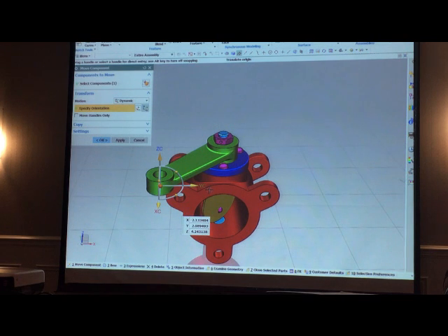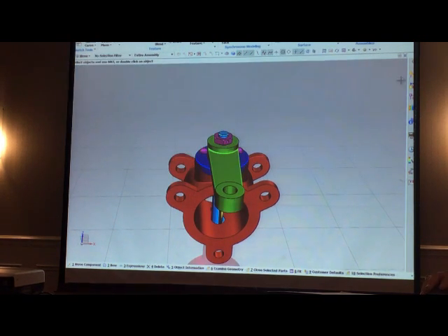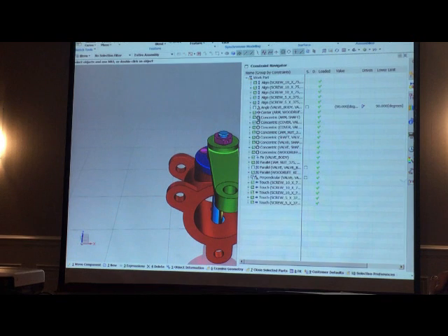I would really like to have the system only limit my motions. So, what I have here is a new constraint, not a new constraint type, but a modification to two existing constraints, angular and distance. These are the two constraints that are driven by numerical values. All the others are driven by other relationships, but those two are driven by numbers. So I've created what we call a driven constraint.